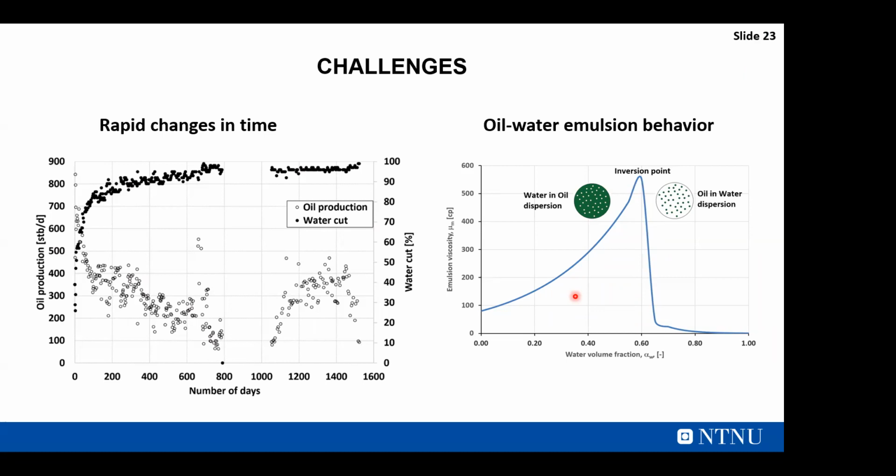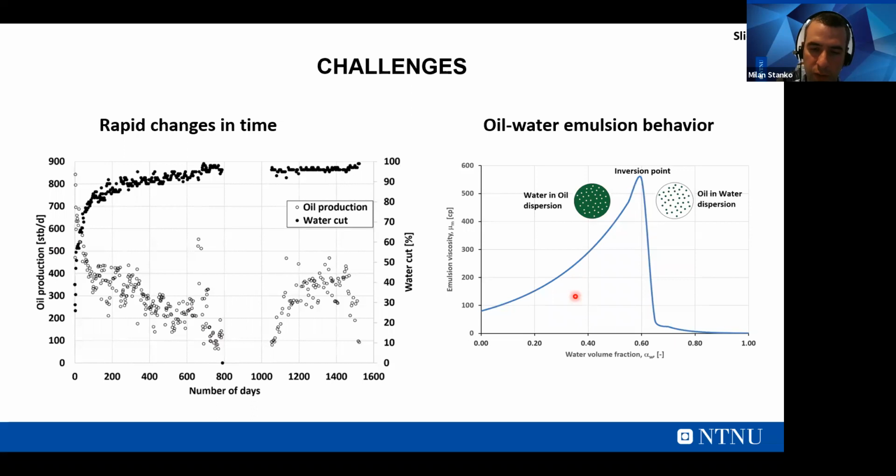From a well test you could get the new liquid PI and the new water cut, and then we substituted that into the model. On the offshore field, we didn't model the inflow because those numbers came from the reservoir simulator. The reservoir simulator provided the rate and the bottom hole pressure, so you only have to simulate from that point up. Sure. Okay. Thank you.